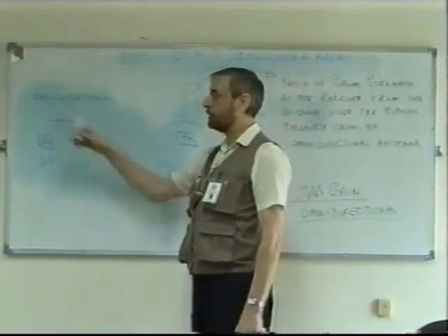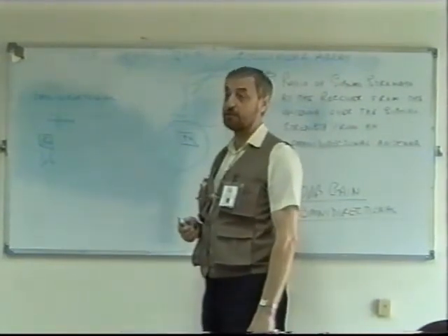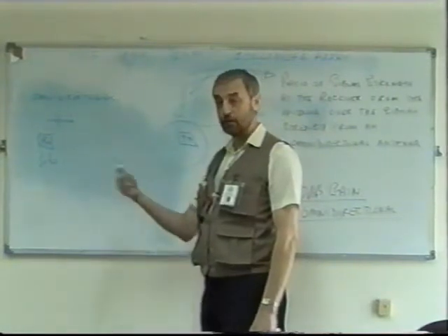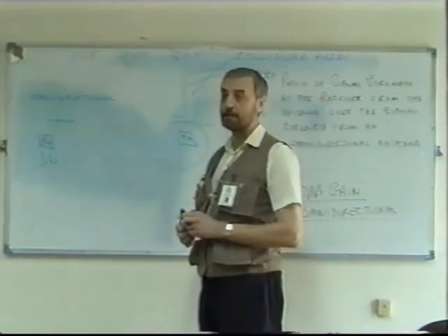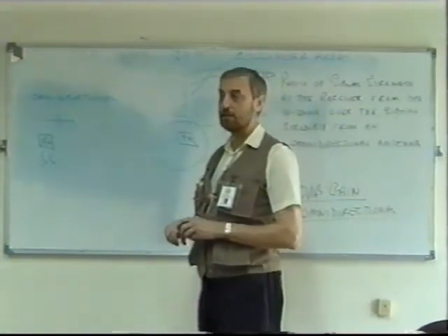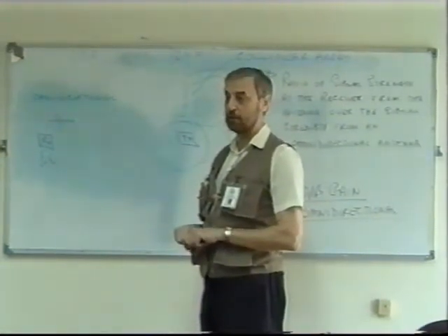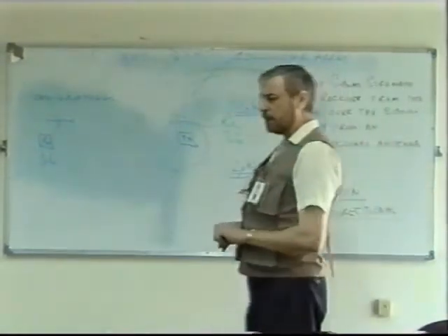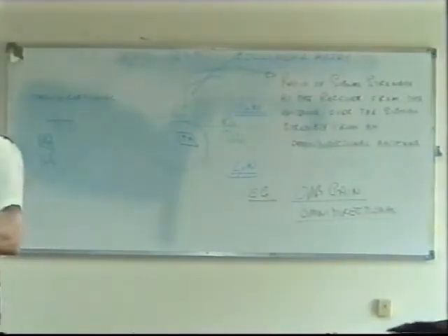But I can also talk about the gain of a receiving antenna, just the same as a transmitting antenna. By making the receiving antenna directional, again you can talk about the gain of the antenna, exactly the same as you can with the transmitting antenna. More or less, whatever we say about transmitting antennas applies equally to receiving antennas, usually. A good transmitting antenna will make a good receiving antenna. A bad transmitting antenna, a bad receiving antenna.